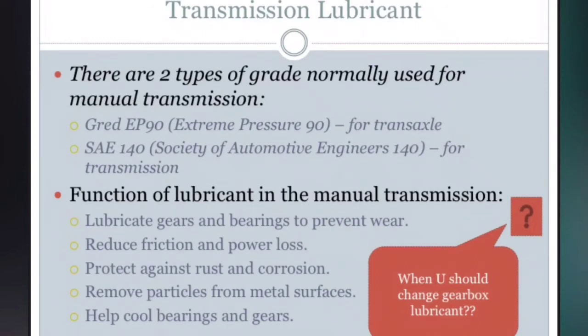Function of lubricant in the manual transmission. Lubricate gears and bearings to prevent wear, reduce friction and power loss, protect against rust and corrosion, remove particles from metal surfaces, and help cool bearings and gears.